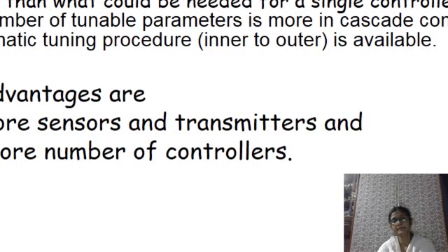And cascading makes the use of feed-forward control more systematic. That is, in the heat exchanger example, it is possible to measure the water flow and add feed-forward compensation. If we use feed-forward compensation along with this, that will definitely improve the speed of response. But even with this feedback system and cascading, it will improve a lot.